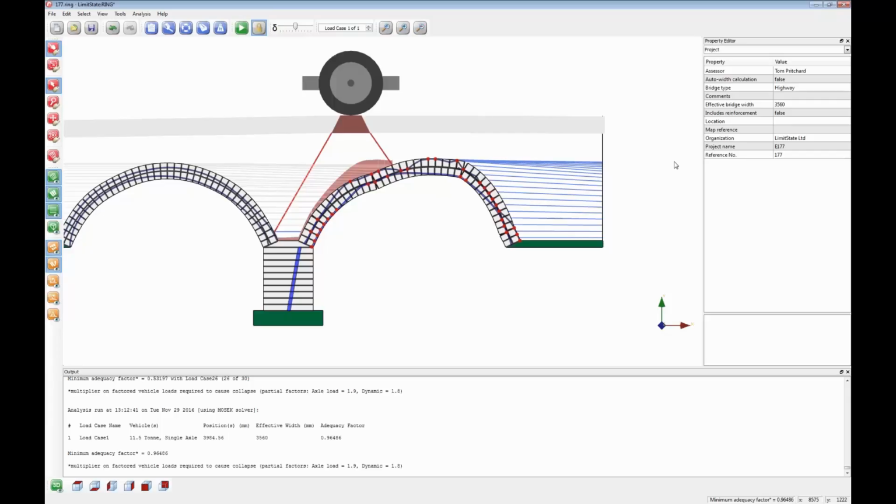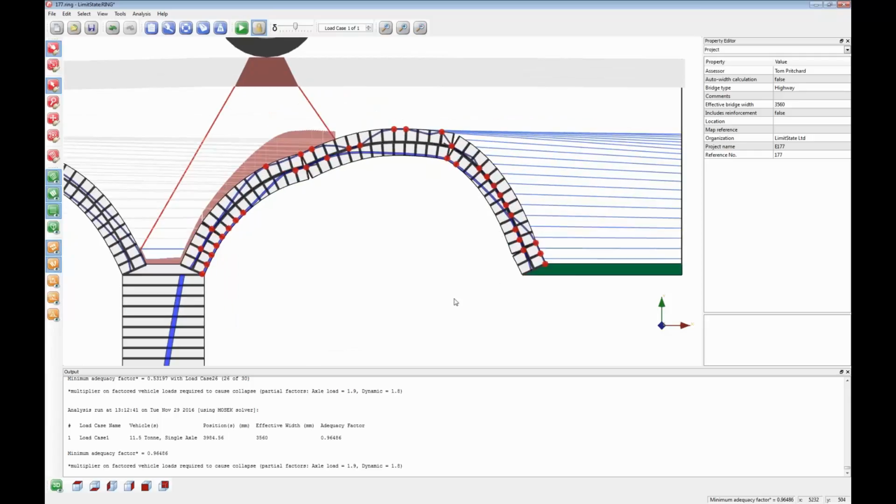One, we have a curved retaining wall, if you like, and two, it's rotating as opposed to translating, and three, I guess, we can't afford to mobilize very large pressures because that would require large movements, and if we have large movements of the arch in the right hand side, then we would end up having gross deformations of the left hand part of the arch, and that would significantly reduce the capacity.